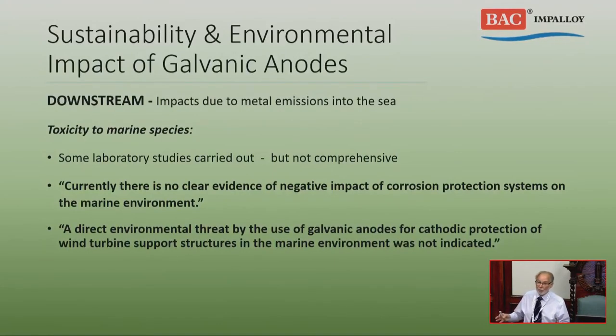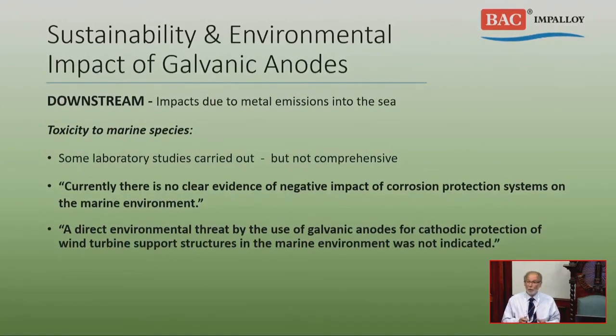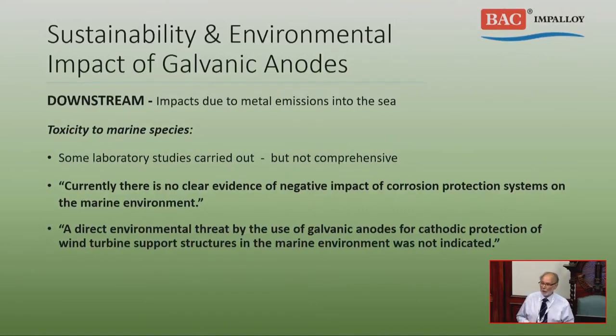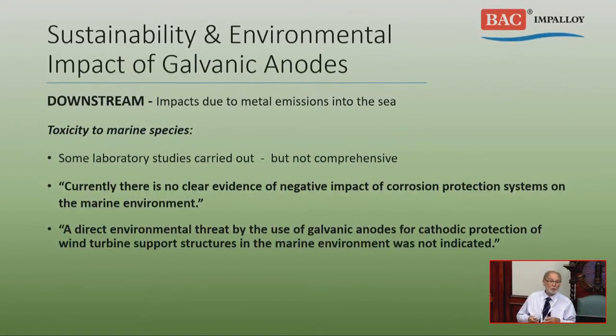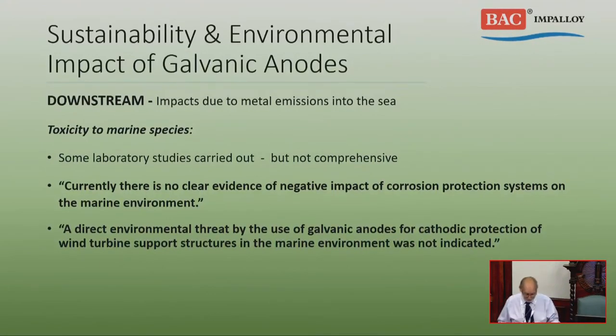But the good news is that we have developed alloys which are zinc alloys which are cadmium free, and we have developed aluminium anodes which have a very low level of zinc in them. And in the new standard ISO 9351, which Birgit referred to, those alloys are included, and they have more or less the same performance parameters as the existing anodes that we use, so that we can have some confidence in the future.